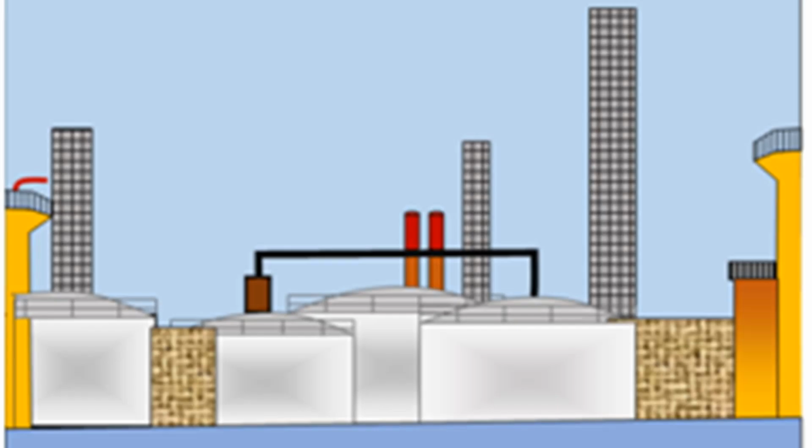The refineries can do this work of blending the normal fuel with a fuel that is extremely deficient in sulfur, so that when the two fuel oils are blended and used on board ship, the SOx that is emitted is in control. Alternately, additives can be mixed with the fuel to increase certain properties like lubricity. But it should be noted that the final product is not harmful. It does not cause more harm than the benefit, so that has to be approved. It has to be approved what additives you are going to use.